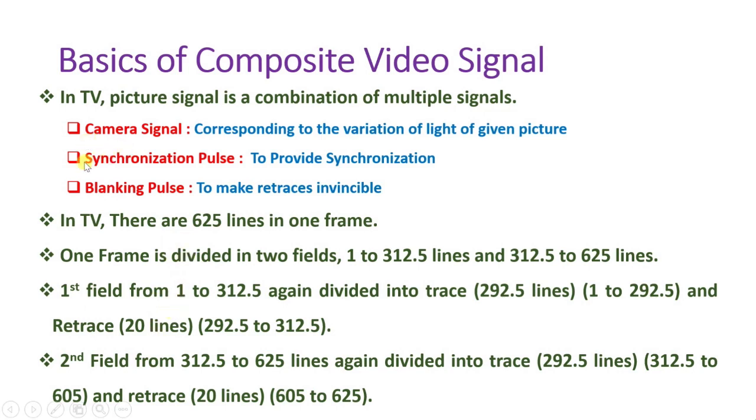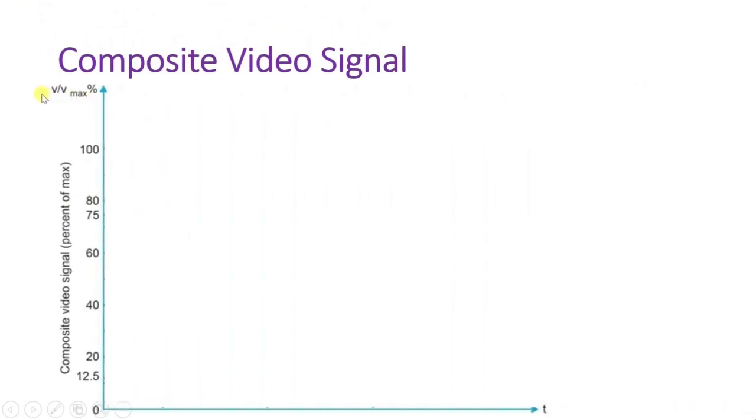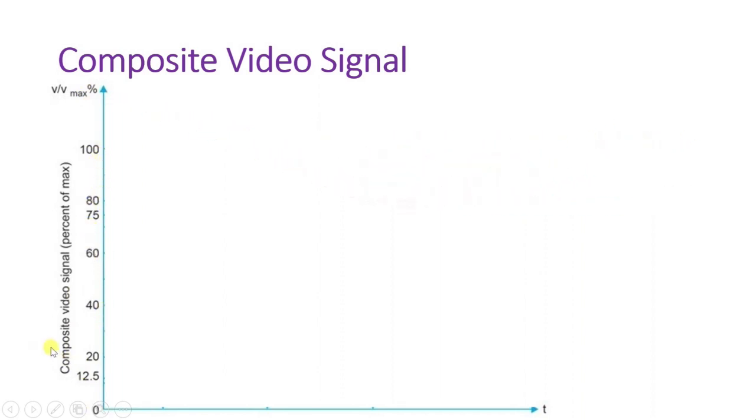As shown in Figure 7.4, there are horizontal and vertical blanking pulses in the composite video signal. Horizontal blanking pulses are included to clear the retraces from right to left within each horizontal scanning line. Thus, the repetition rate of horizontal blanking pulses is a line scanning frequency of 15,750 Hz. The vertical blanking pulses clear the scanning lines that are produced when the electron beam retraces vertically from bottom to top in each field. So the frequency of vertical blanking pulses is 60 Hz for each field.